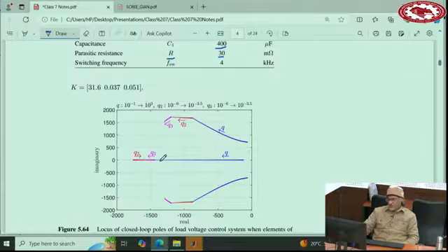Then let's say at some point you stop Q and increase Q2, then you will see this behavior. These go down with a little bit more damping, but the other one starts coming back. And now once you apply Q3, you will get more damping, and this pole also will move to the left. So you would like to have these two poles, these two complex poles, to have sufficient damping, and this real